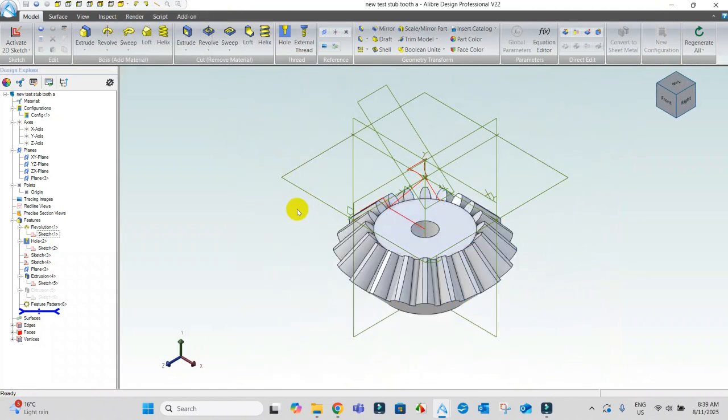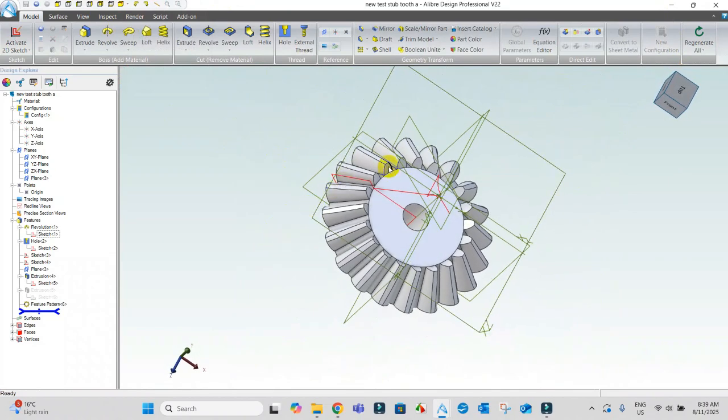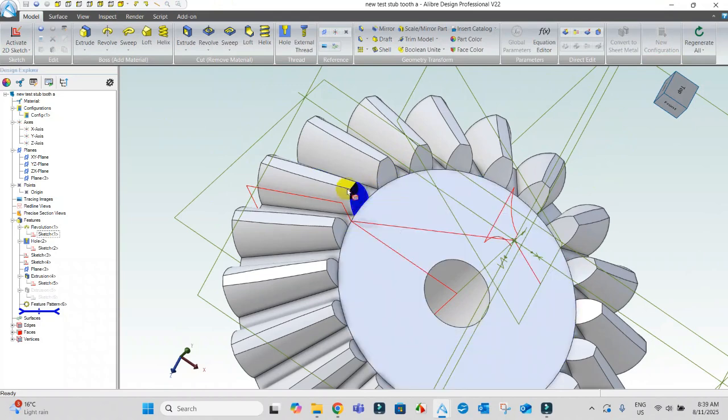There is the same gear as I did before, except that it is stub tooth form. So you see here the bottom of the cutter, it's the same cutter, but this runs very parallel across the top there and for a lot longer because the 0.25 is missing from the top of that, and this is shallower, so the face of the teeth is effectively a little bit more vertical, which gives me a little bit more leeway. It does have a little bit of an impact on the engagement. We'll have a look at the model itself.